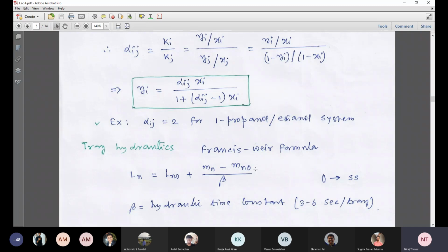You can easily calculate the volume. Now, suppose 80% is defined in the tray geometry: 20% of the tray volume goes to the downcomer. Rest 80% remains for the liquid holdup.